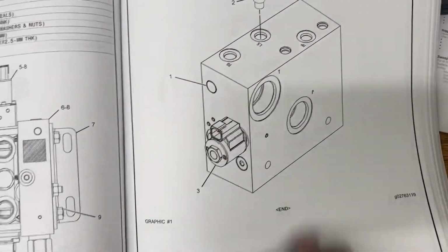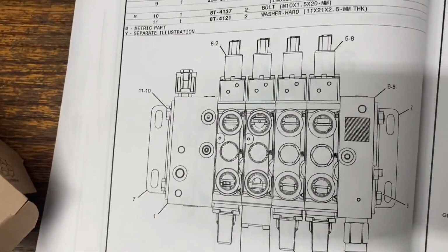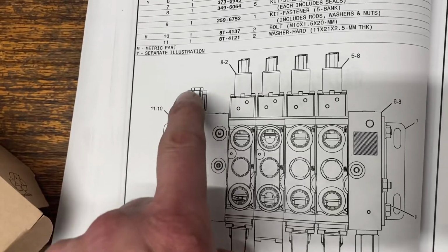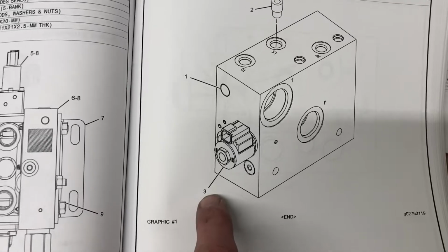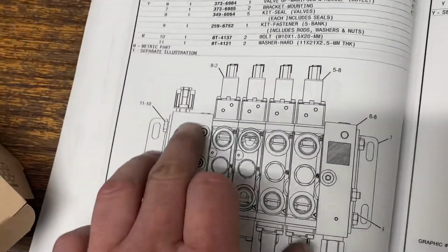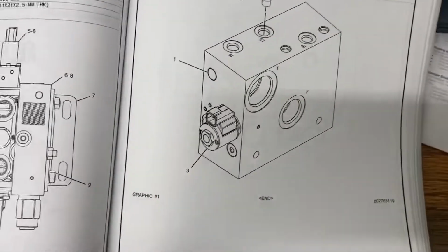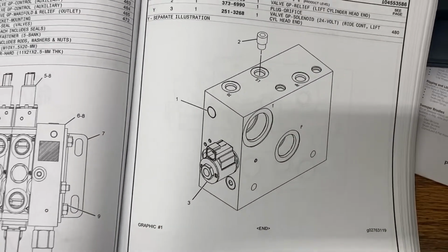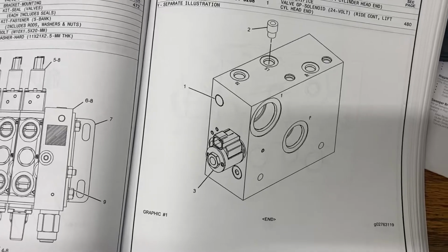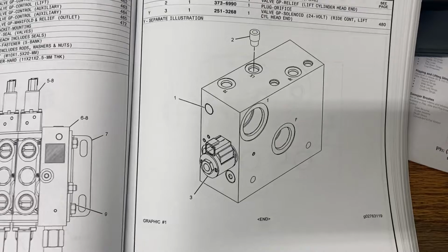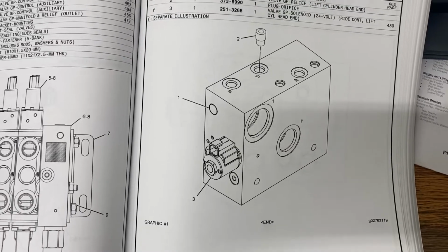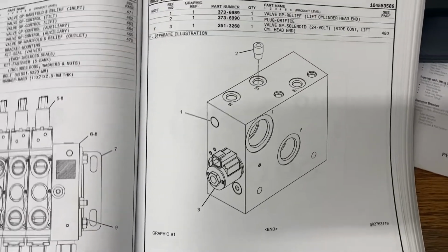Well, look at this. Now they just show you one part of the hydraulic control valve. They don't have anything identifying the valve that we need. But anyway, it's number 3 here. So that's this part of the control valve, sandwich valve type thing that bolts onto the end. This is going to be your supply. Now remember, our code in the machine on the monitor, the warning that it's going to give you says implement fault, implement solenoid valve fault, implement supply is the code that you're going to get.